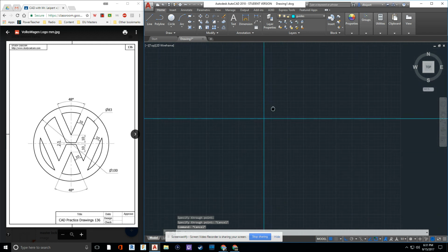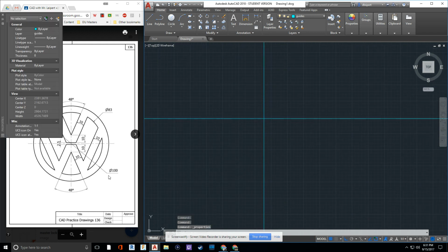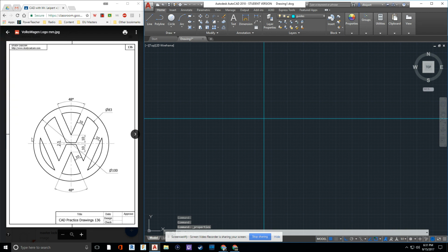These crosshairs right here are going to represent the crosshairs that are right on here. So I'm going to now go off of this and create this as my center point for my two circles that swoop around. I'll make the circles in my object layer, and I'm going to make that a center diameter circle. Snap to the middle. If you don't get the snap, toggle F3 on your keyboard, and that would turn on your OSnap. If you still don't have it, type in OSnaps, and you'll see that as an option to snap to the intersection. 100 is our diameter on that circle.